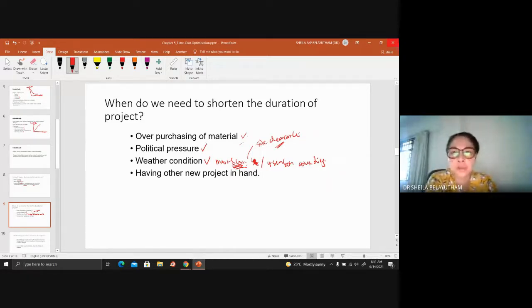So for site clearance on such area, okay, on such state, you might want to do it much more earlier. So if your project starts in August, most probably you still have time to actually complete your site clearance much earlier. So hence, you can actually start on the building itself. Okay, so if you have already done the foundation and the slab starting, then it is not too bad. Okay, so for you to actually have your construction still ongoing, but at least reduce all those pollution that you might cause. Okay, so weather condition on earth, it is a lot to actually reduce the site clearance or earthwork during the monsoon season.